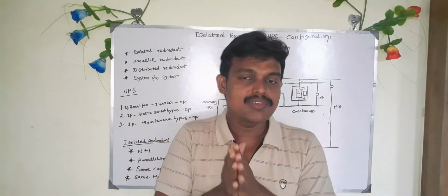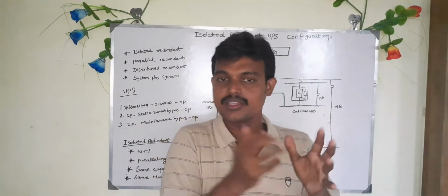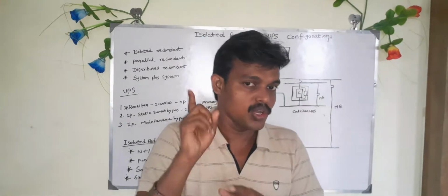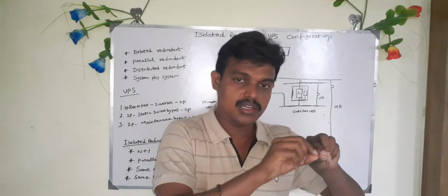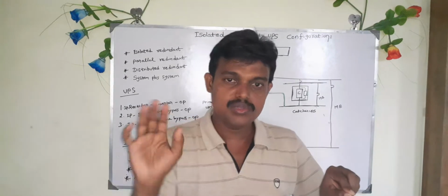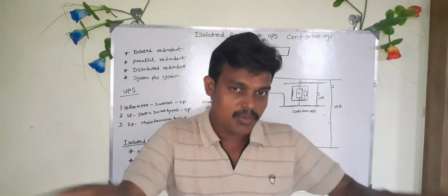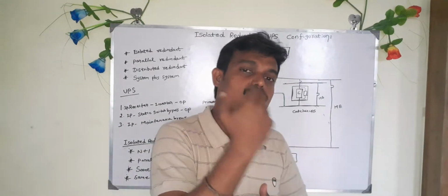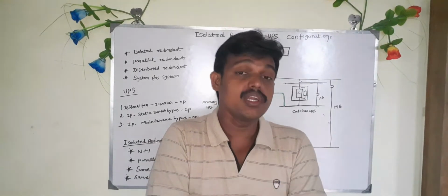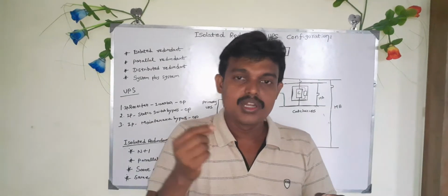However, the UPS will select automatically, based on the situation or failure event in the UPS, but it will select only one mode. Generally you are sending the power through the double conversion mode. If any event occurs in the double conversion mode, it automatically transfers the load to the static bypass switch, without interrupting your power supply.